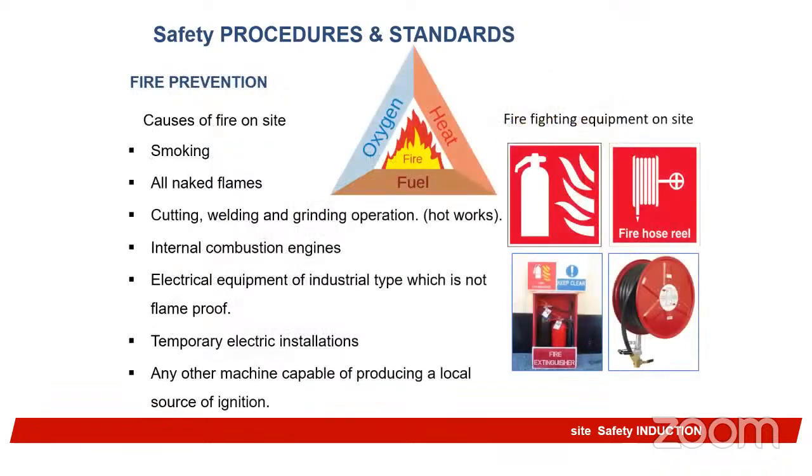So they talk about fire prevention. We talk about no smoking. We talk about what can cause flame, what can cause fire: smoking, naked flame, cutting, welding, internal combustion engine, electrical equipment, temporary electric installation, any other machine capable of producing a local source of ignition. So you should talk about everything based on what we have on your side. You know your facility already, you know where there can be fire, what can bring up fire.